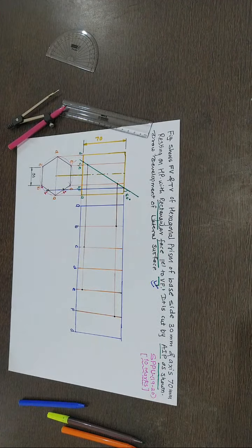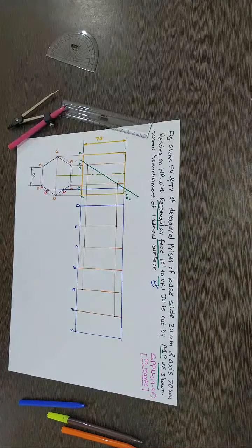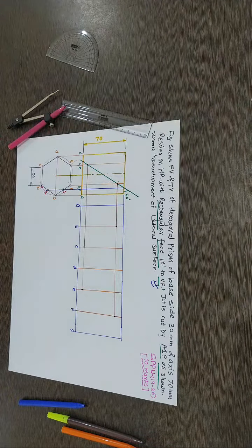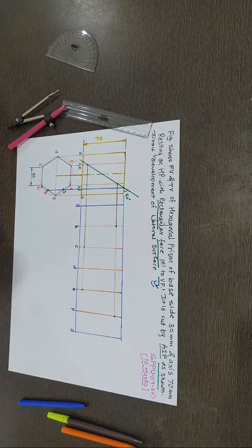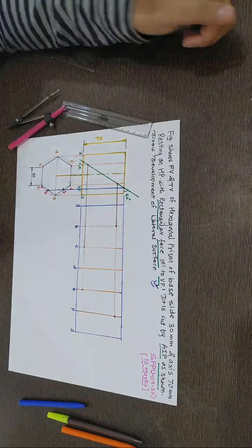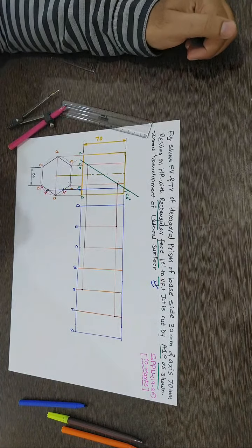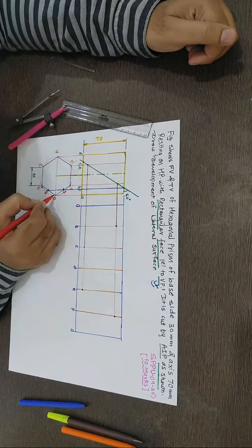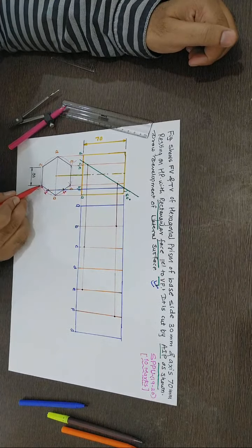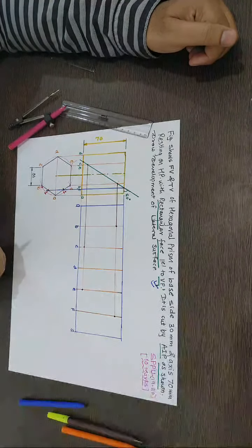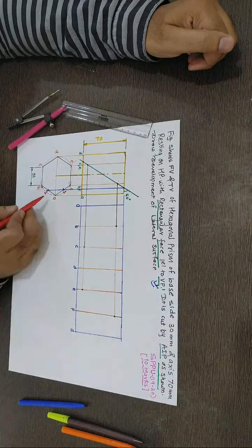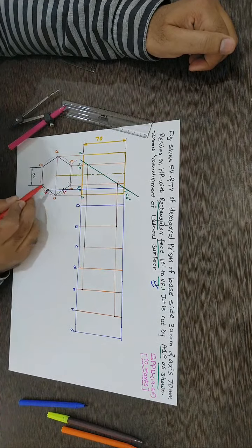So if you extend the top face in the top view, you can see the 2 points, namely 1 and 2, and the corresponding edges of the base: point 1 is in between A and F, point 2 is between A and B. Now you need to represent this complete edge, right?